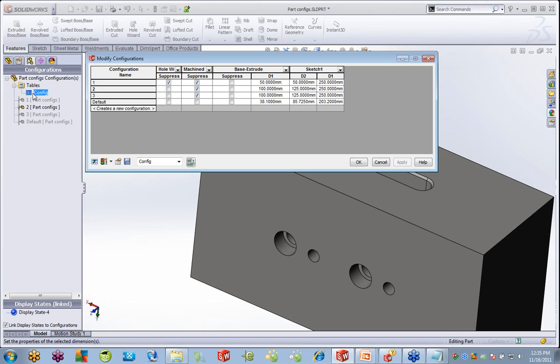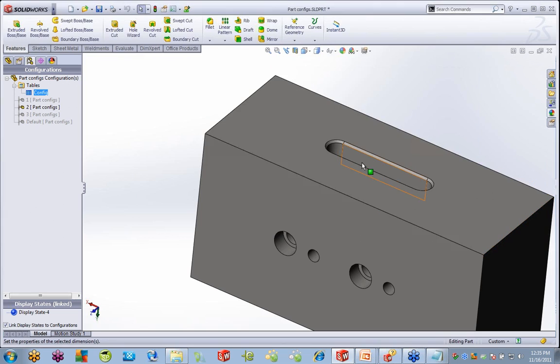It clearly isn't there because you can add material, you can add features, suppression state of features, sketches, and dimensions. But you can't add things like center of mass and all these other things that we were discussing. So it is very limited, but for a decent subset of folks, I can create a nice interface for being able to modify and add configurations. So this modify configurations dialog box can be very useful to some folks.